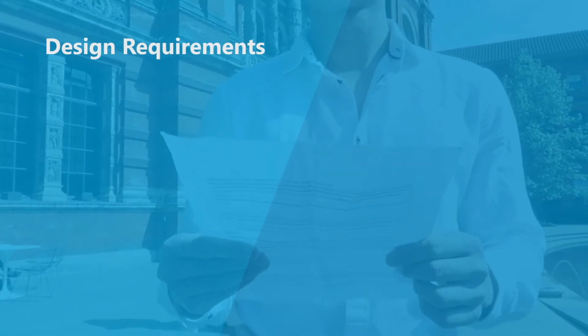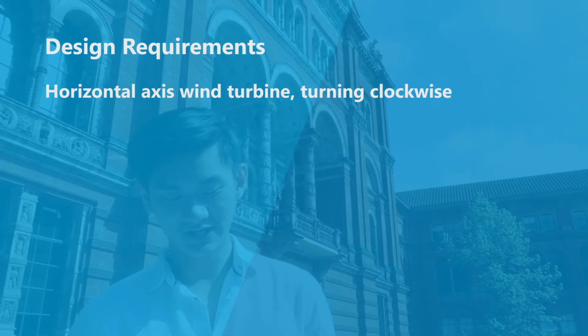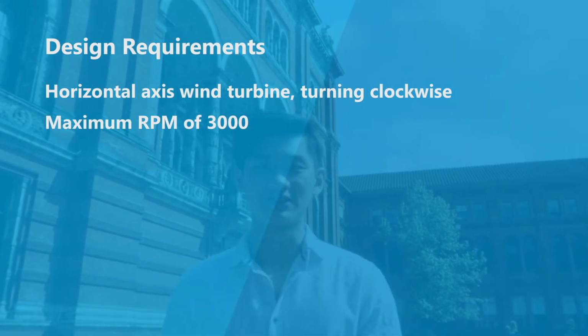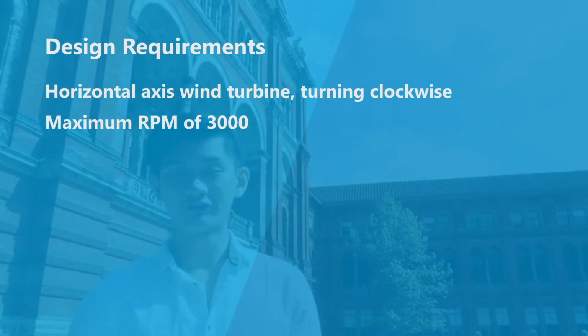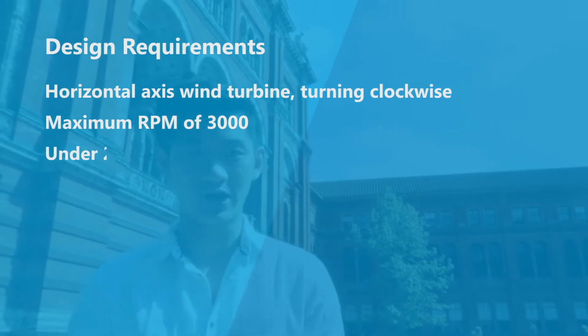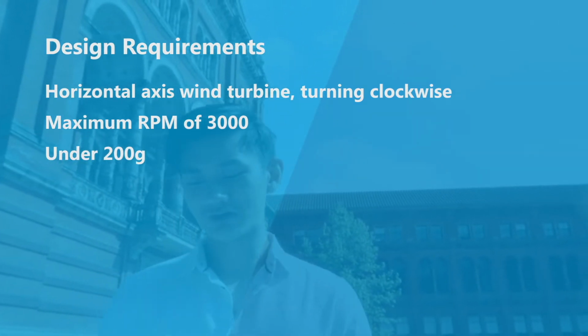So, a team of 6 aero students who totally know what they're doing set on task to design a mini wind turbine. The design requirements are: we have to create a horizontal axis wind turbine. 1. The blades should turn clockwise when viewed from the front. 2. When rotating, our maximum angular velocity must not exceed 3000 rpm. 3. Our wind turbine can have any number of blades, but it has to be below 200 grams, and it has to fit inside a box with dimensions 400 millimeters.